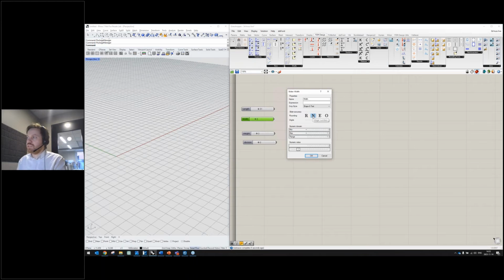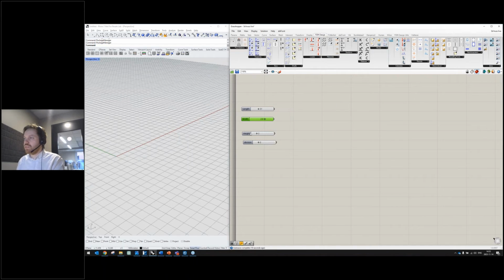Now it's set to integers, whole numbers, but for the width and the height, I want a floating number with 1 decimal, and maybe the max value should be 3 meters, and the same for the height. So now it's like 1 point something up to 3 meters. But the division should be a whole value. Let's say that I want this up to 15 as maximum.